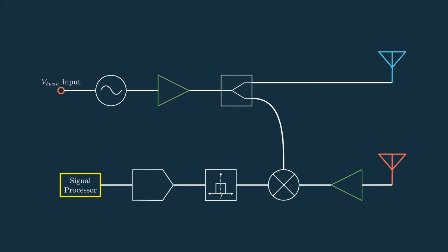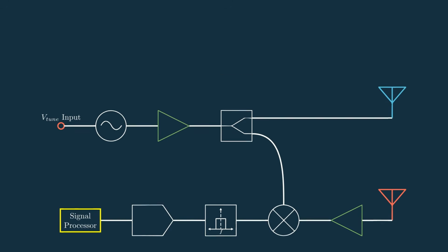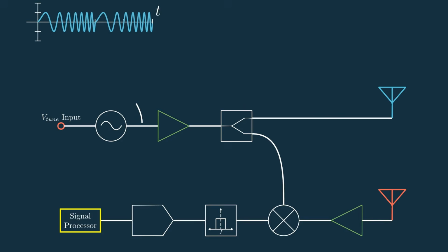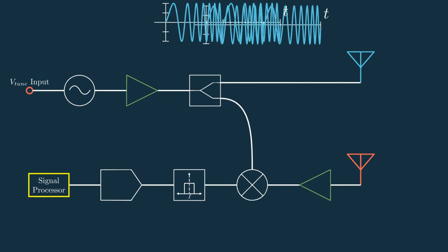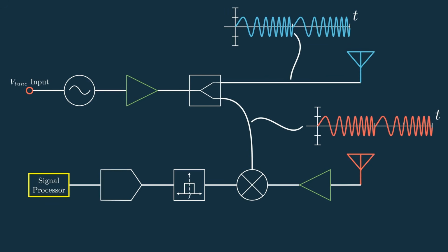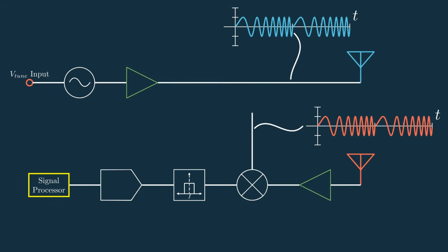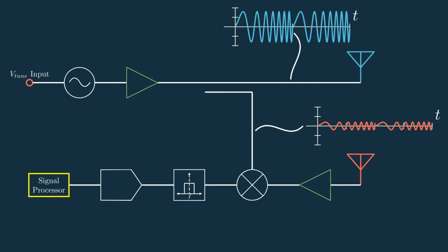Okay, so the first block is done. Let's pull back from that signal generator block and head back to our main block diagram. Once our frequency modulated signal is generated, we send it to the next stage to be amplified. Then it is split into sections for transmit and receive, often using a splitter which splits the power in two, or we could use a coupler which wirelessly couples a smaller amount of the power from our main transmit path to the receive path. And then the transmit waveform goes to the antenna to radiate into the world.